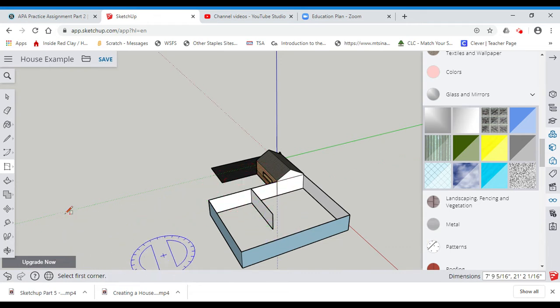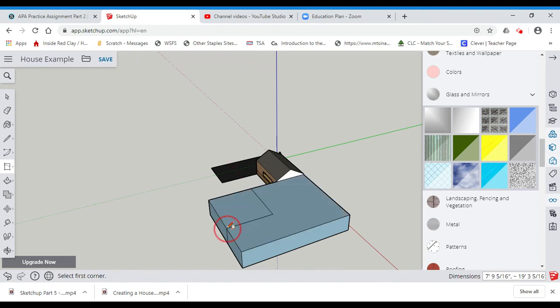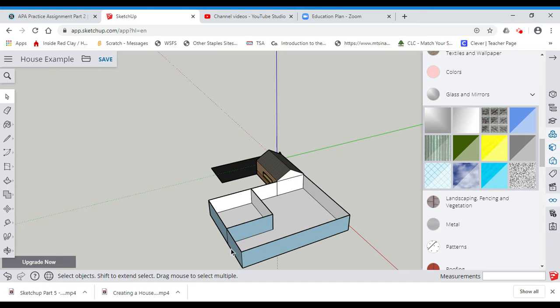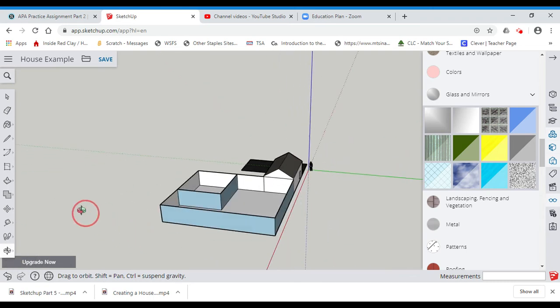Pretty cool, right? So then I need a wall closing this out. So I'm going to start from the bottom, click here at the top, and then drag that wall all the way over here to the edge. Pow. And there's another wall. Now you know how it closed up the top? That's fine. You can just delete that and delete that one. And there you have your nice little room. And so now you can do some additional rotating.